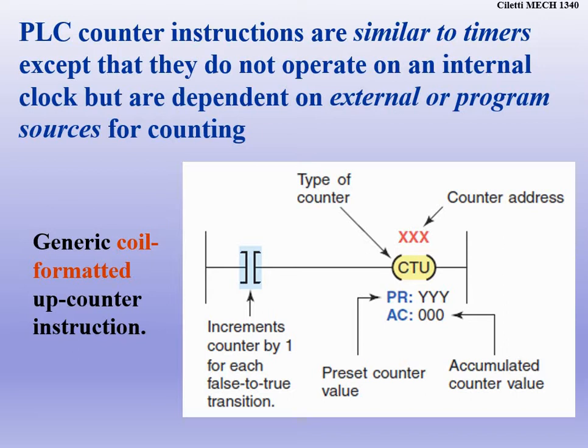We talked about this in electrical class when we talked about signal analysis. We also talked about this in digital electronics, when we did flip-flops and things like this, we were always basing things on the rising edge of the clock, when the clock went from 0 to 1 or false to true. That's what's going to trigger our up counters here. So think of that as that manual button you're pushing, or we have a sensor, and every time that sensor goes off, we're counting what's going by.